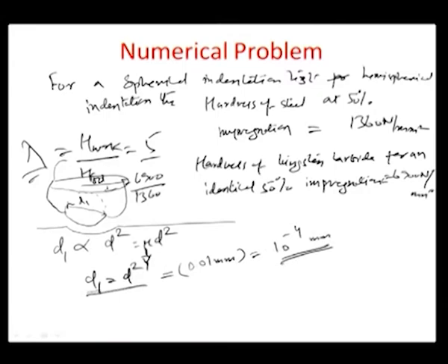So, this is just a correlation equation. It is not dimensionally correct though, but it is some kind of a correlation numerically between the value of d1 and the numerical value of the average diameter of the grain d, without looking at the dimensional aspect of it. So, the grain diameter can be, from experiments that Shaw did over a microscope, predicted as about 10 to the power of -4 millimeters; this is the effective grain diameter of the surface. And while doing this, there is an indentation HW that the grain would like to have on the surface here.